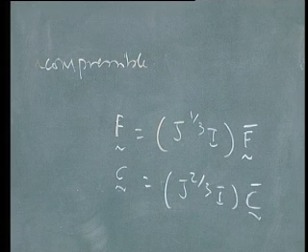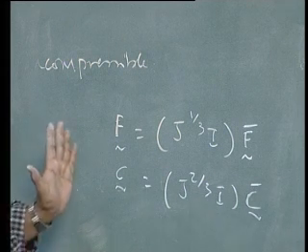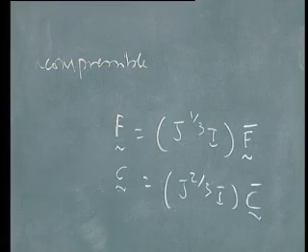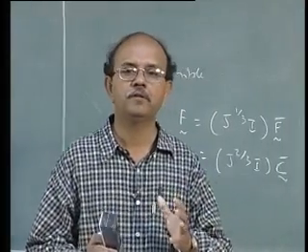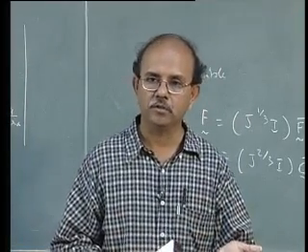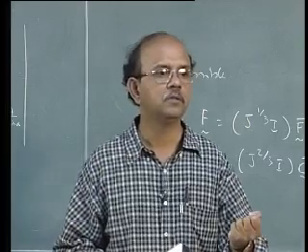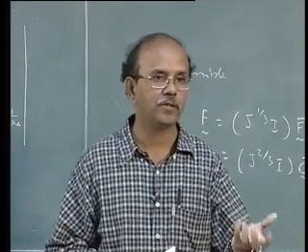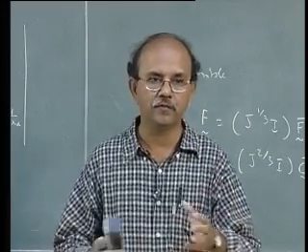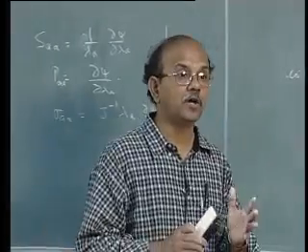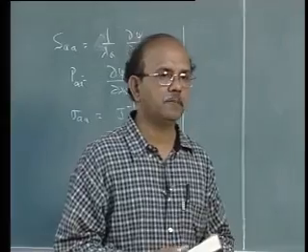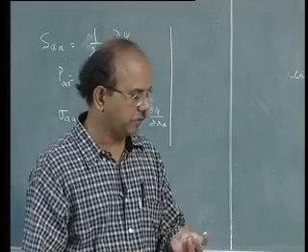So what we now do is that there is a deviatoric and a dilatational part. We say that there are two versions of psi, the strain energy function. One is due to the dilatational, volumetric part. The other is the isochoric part, where there's no volume change, or deviatoric part. So we put down two psis. Before that, let's write down some expressions which we may need later.